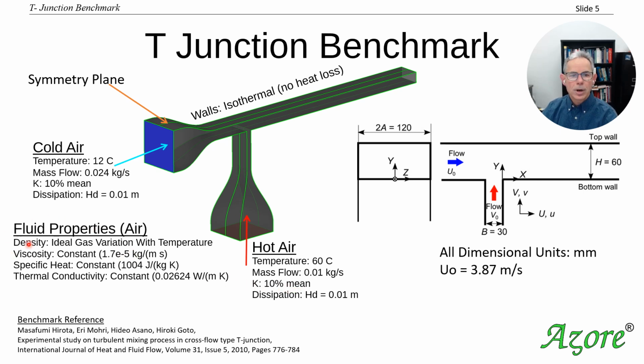For the fluid properties, we're going to assume that the density is variable with temperature using the ideal gas law. The viscosity we're going to assume is constant, as well as the specific heat and the thermal conductivity. And those values that we chose are right here.